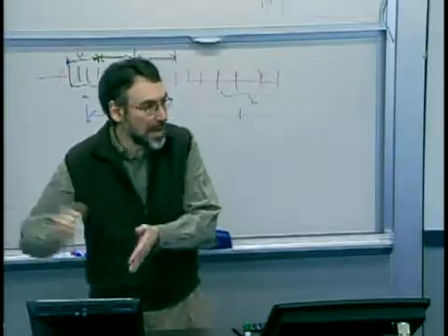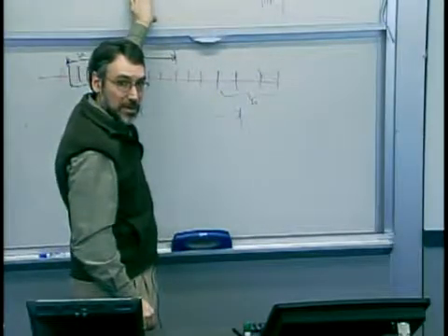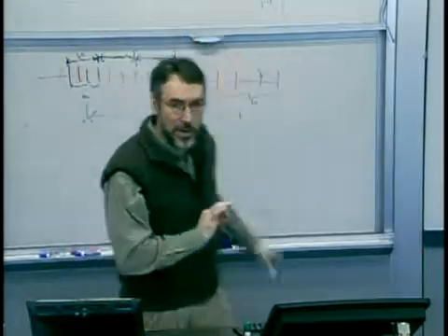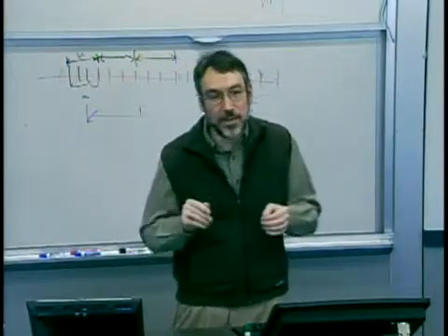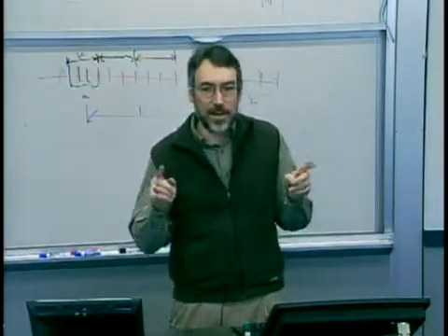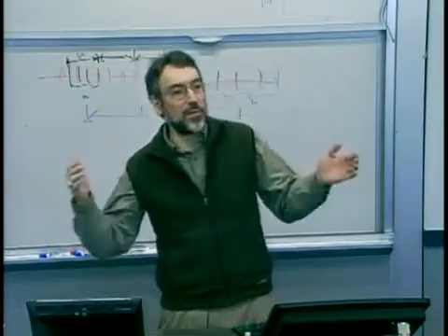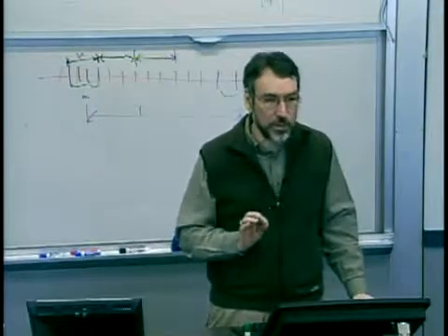You don't use the spec limits to set your control limits. Control limits are based on detection of unusual events, and that's based purely on your model. You might superimpose your spec limits to be able to quickly calculate and think about what the probability of non-conforming parts are, but those are different things.